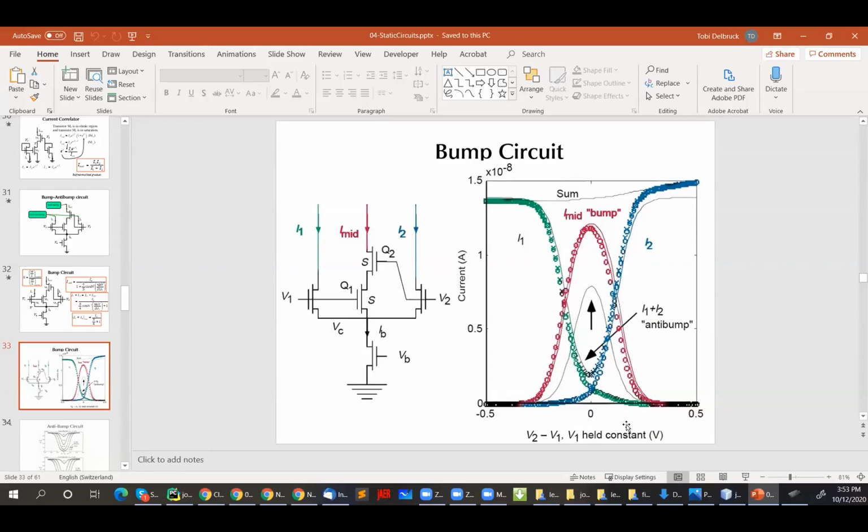You do use that quite a bit, right, in different ways in your neuromorphic circuits. You might want to measure whether the voltage of some circuit is close to some reference that you care about. Imagine it could be in a control loop: if it's too far away from the reference voltage, then you want a current to flow that does something to make that voltage close to the reference, right? And when it's close together, you might not want to change things anymore. So that's how it's been used over the years.